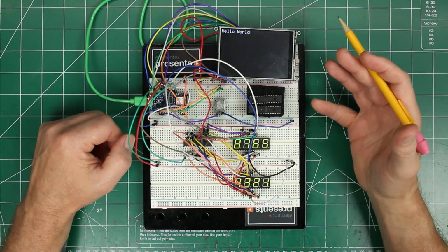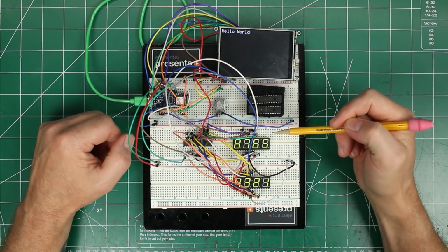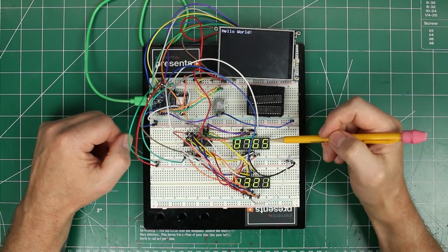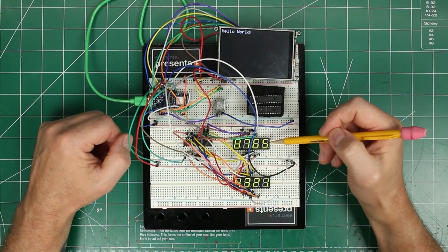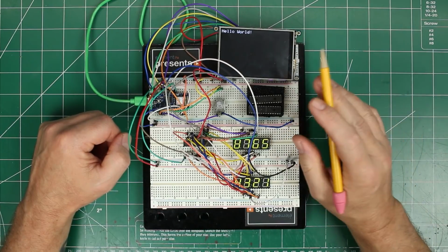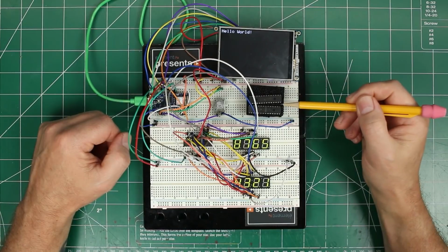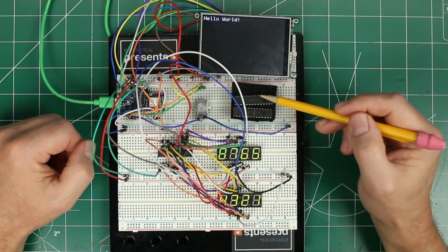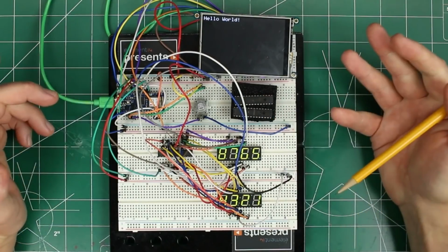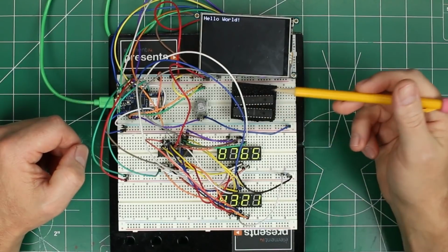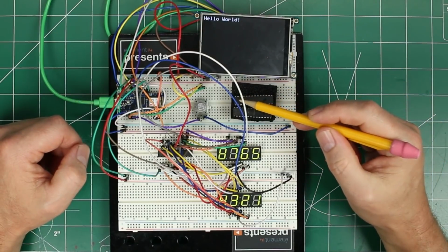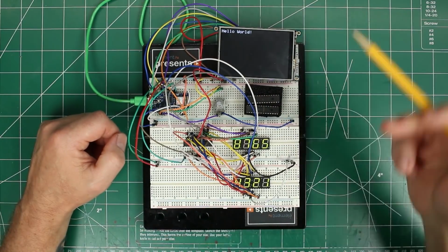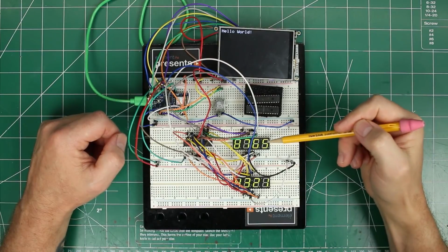The way I understand it works is it's all about the refresh, turning the LEDs on and off so fast and in such a way that you can see these digits and you can't see the segments. So when I had that hooked up through the MCP, it just wasn't fast enough, because the library I was using didn't support the MCP, and I wedged it in there. There's a good reason why it didn't support the MCP: it had to digitalWrite every pin to turn it on, and that took one cycle of the Arduino for each one of these.